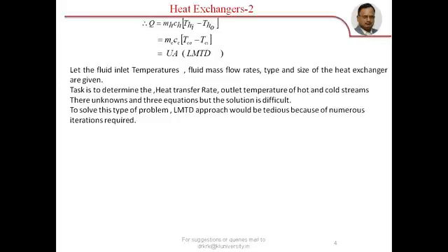So that leads to development of another method instead of LMTD method. It is effectiveness NTU method. So we follow effectiveness NTU approach to determine or to design a heat exchanger when both outlet temperatures are unknown.